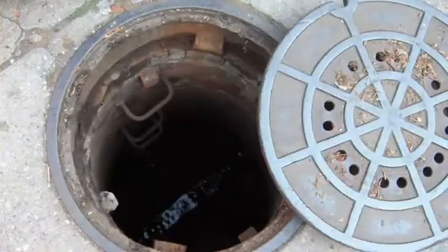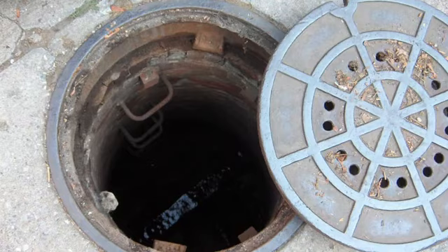They may have modeling based on this. They may have all kinds of engineering analysis based on that 12-inch channel, when the reality is they have something completely different. The other advantage of doing a manhole inspection is it identifies cracks and whether they need any kind of rehabilitation. We don't provide that service. We give this data to the city.